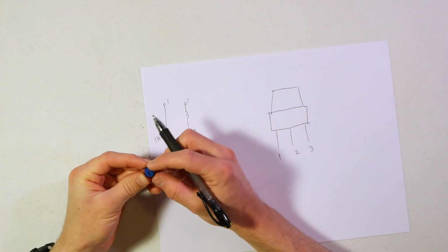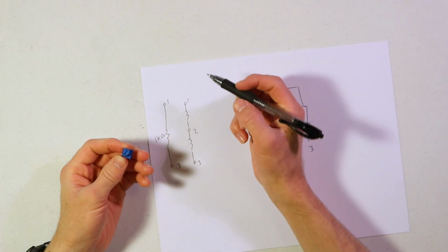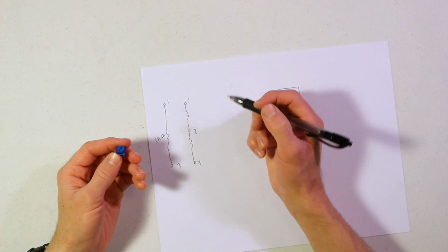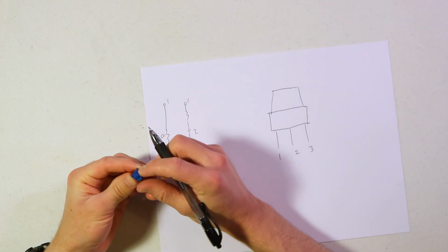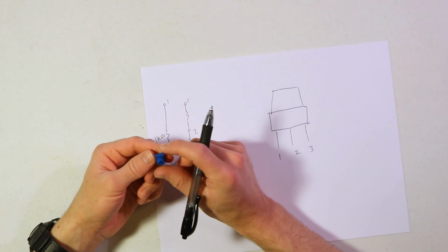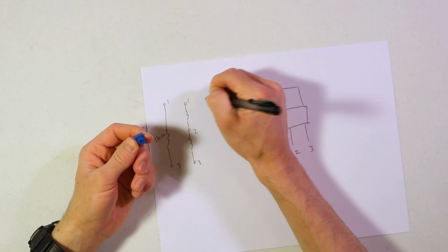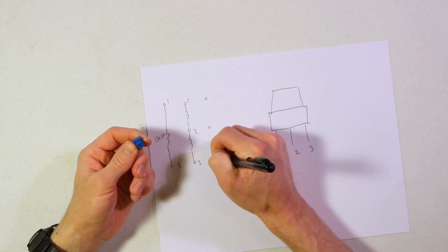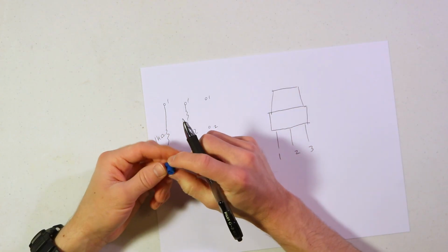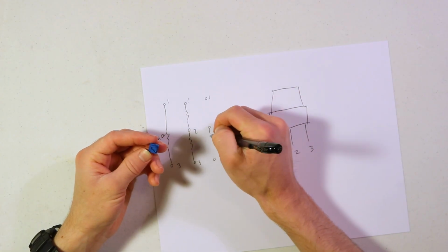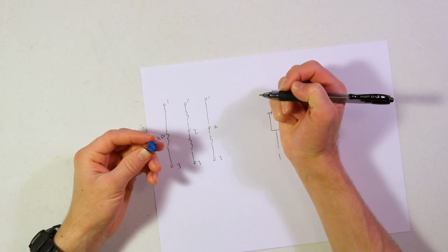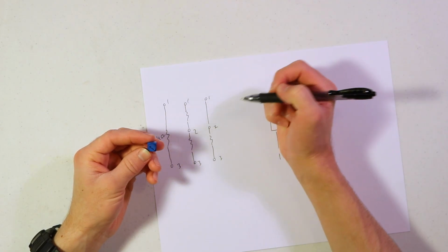So as we twist this knob, we're going to see more and less of the resistance across, say, 1 to 2 and then 2 to 3. And if we twisted it to the extreme, like let's say we twisted it all the way here to the left, then we can have pins 1, 2, and 3. And now all of the resistance is going to be between pins 2 and 3, and none of it is going to be between 1 and 2. This is just going to be like a wire between them.